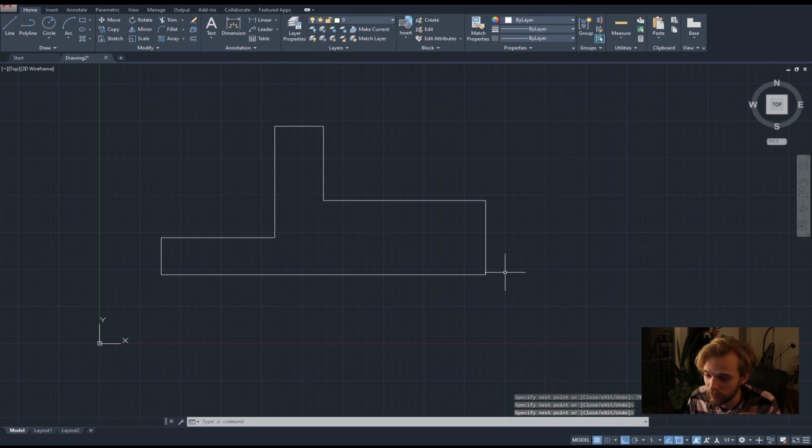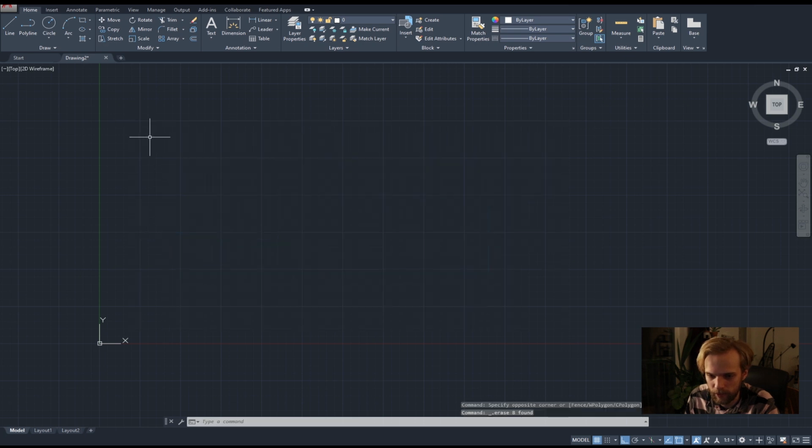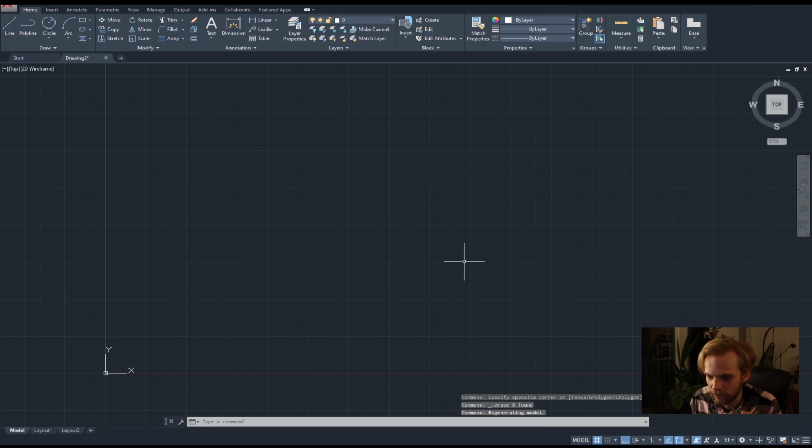So that's quite useful. I will show you later a few more tips and tricks in terms of the angles and snapping to different angles, but turning ortho on and off is one of the smoothest, or most useful workflows. Let me get rid of this. So that's how you work with lines and horizontal and vertical snapping of lines. Let me turn off ortho for now. So I either click on this icon or just hit F8, and I can see that icon is turned off now.